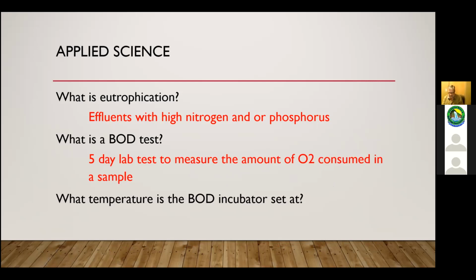So when you do a BOD test, what's the incubator set at? What temperature? And you're going to see this question for sure. 20°C. So make sure you commit that one to memory.